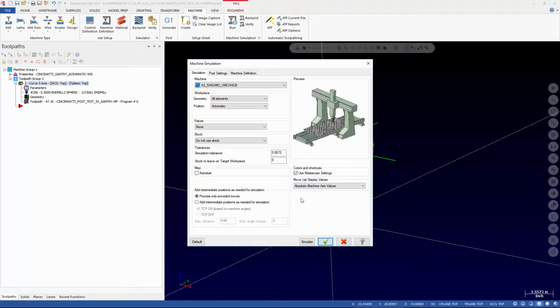Let me see where this is at. Position. Translation in XYZ. And this is exactly what we got going on. So you can see it's automatically putting a translation of -9 in there. If I left it 0, it would be, you know, 10 inches up top, but the origin of the machine's at this back corner. So we're going to go like -30 in XY. And then because we've probably got it on some kind of riser or something like that, I'm going to put it up another 15 inches in Z.